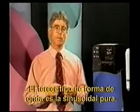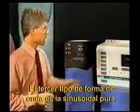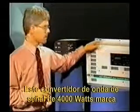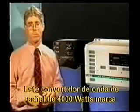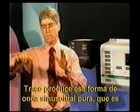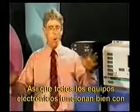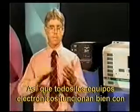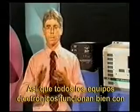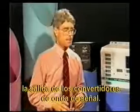The third type of inverter output waveform we should talk about is pure sinusoidal waveform. An example of an inverter that produces that might be this Trace 4,000 watt sine wave inverter. Now we're dealing with the expected sort of pure sinusoidal waveform that we get from utility power. So all types of electronic devices, delicate electronics and radio equipment and so on will operate just fine from the output from sine wave inverters.